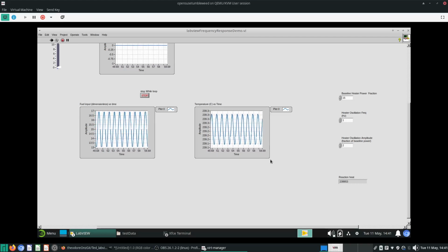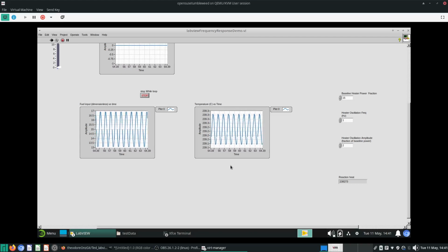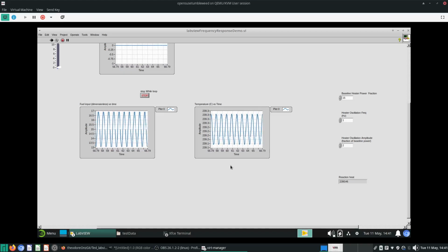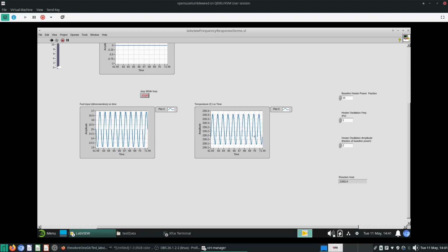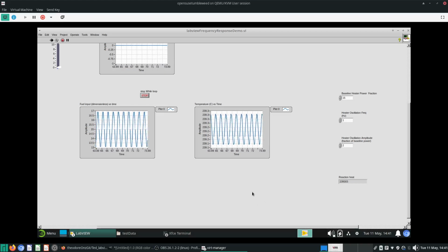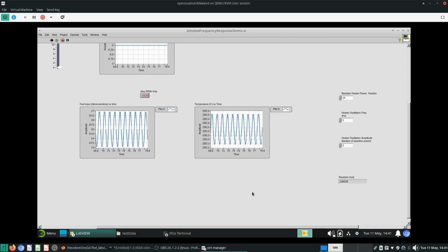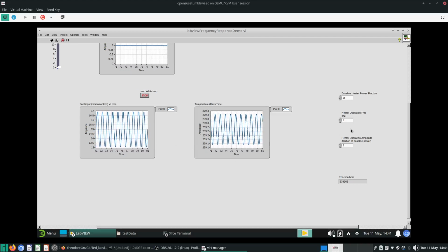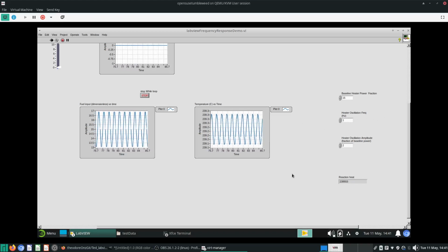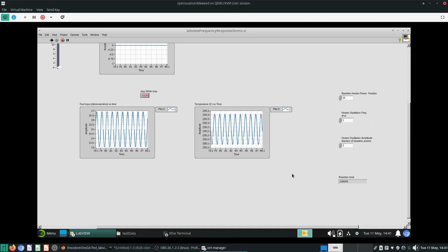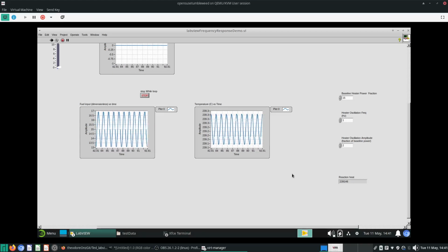And this is how frequency response is done. You take a look at the input, you take a look at the output, and you just run it over. As long as this thing stabilizes into a sine wave of sorts, you should be able to use that data. For very high frequencies, a relatively high frequency for this system is about 1 hertz, which is more than any of the poles we might get, more than any of the typical process times.